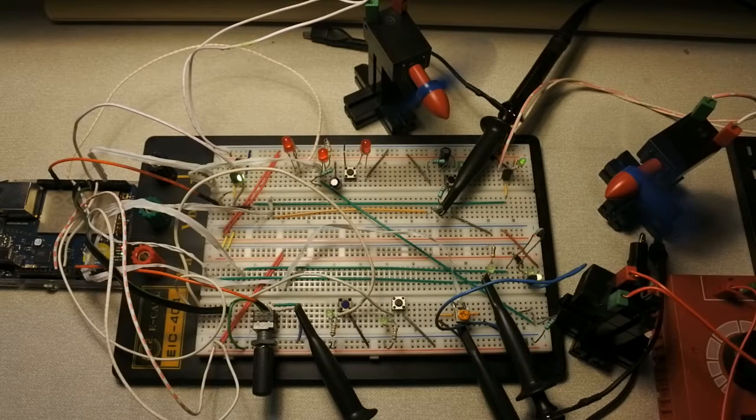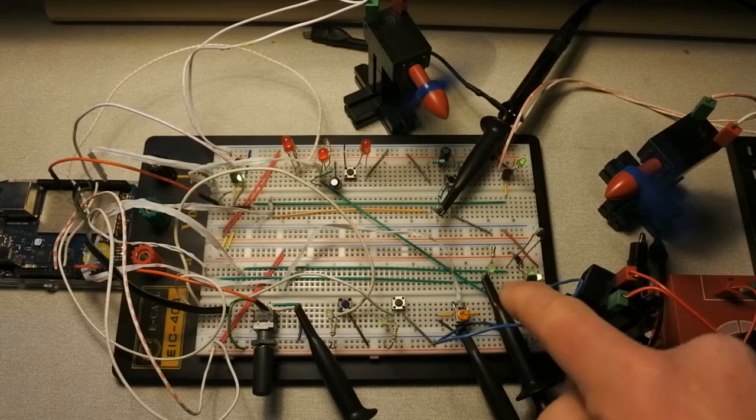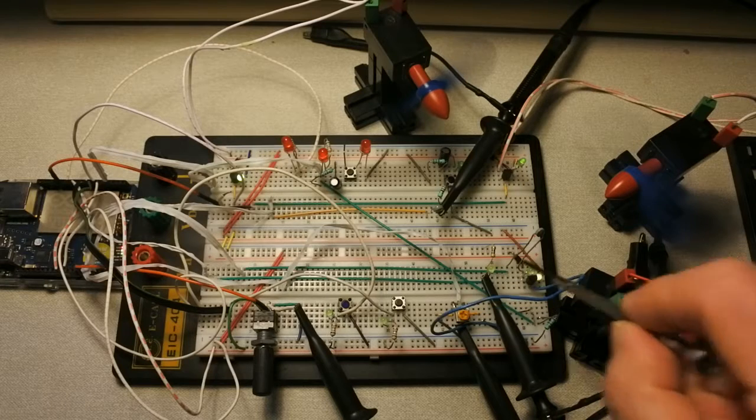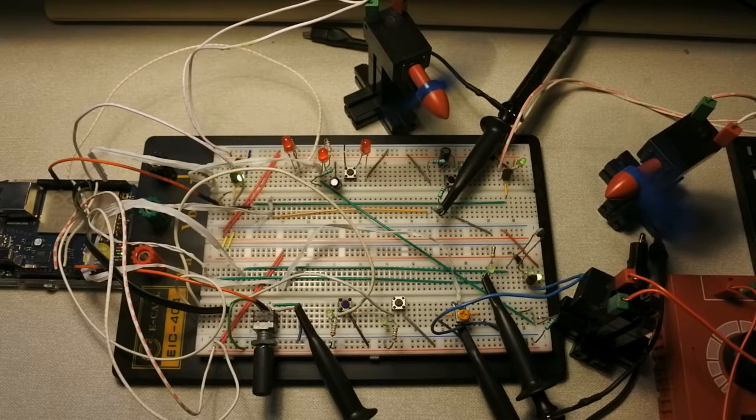Last time I found why this LED did not work, and that turned out to be a matter of, of course, pulse modulation, since pulse modulation is what the outputs of the Arduino give, but the culprit turned out to be that the maximum value of the output to which this LED is connected is not 10 bits, but 8 bits, and 2 to the power 8 is 256.